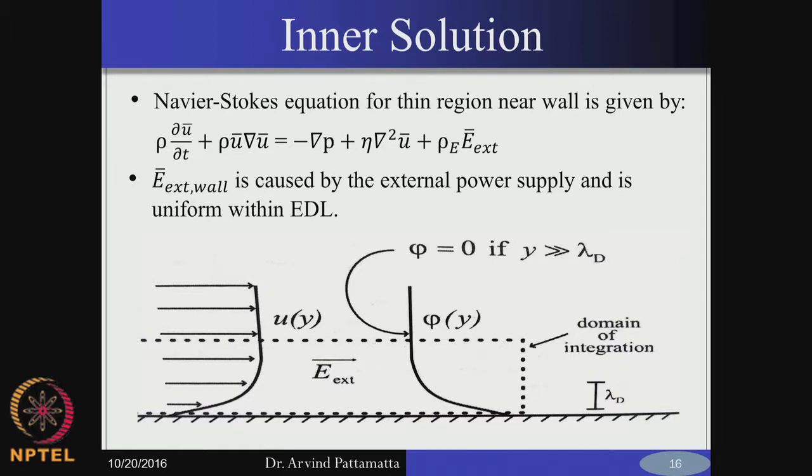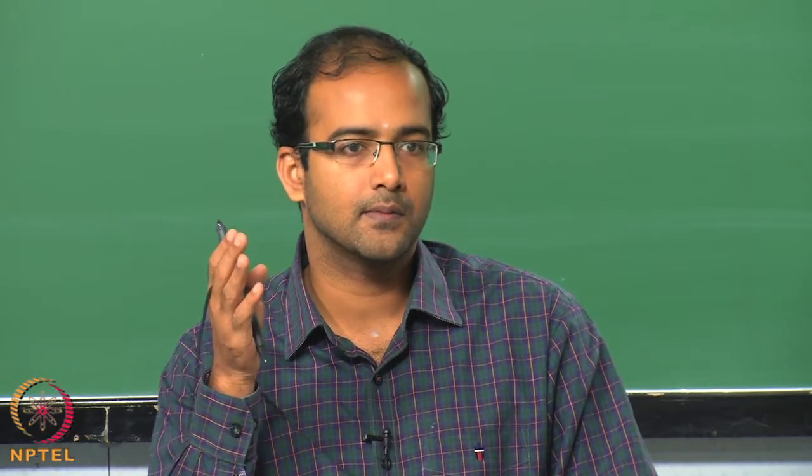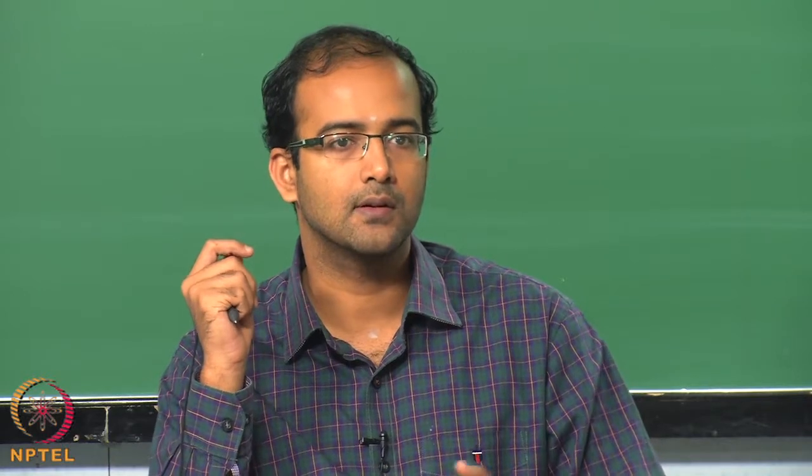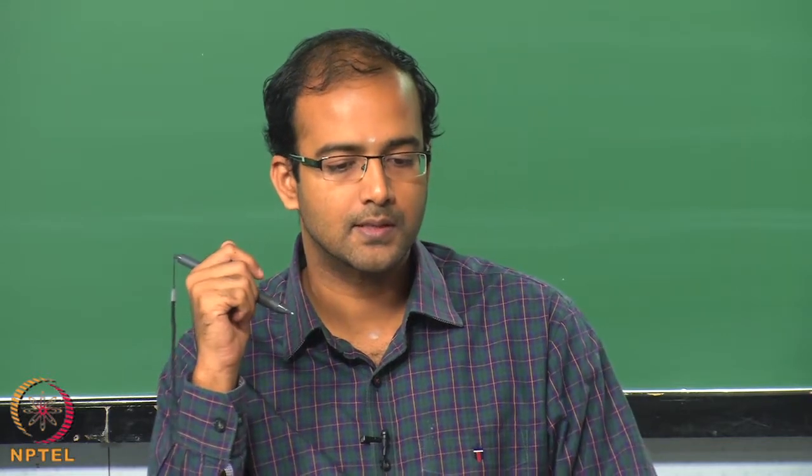But again you should remember that the mean free path is also very small for liquids. So, therefore, you might still be in a Knudsen number range which is much less than 0.1. So, you do not have to really worry about breaking the continuum assumption, whereas for the same length scale, if this was gas flow, definitely not, correct. So, the same continuum Navier-Stokes equation is written.